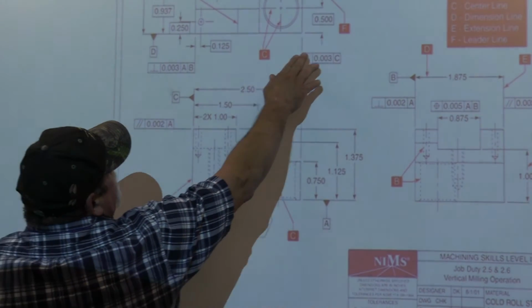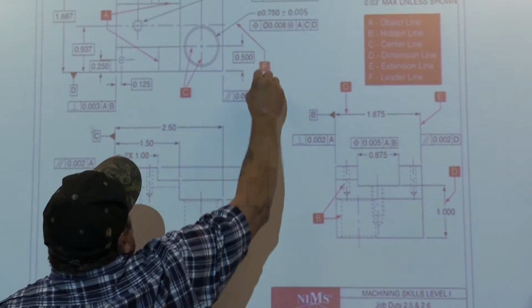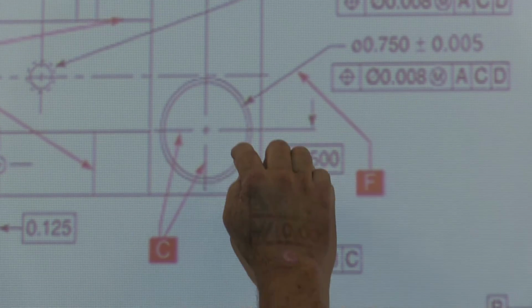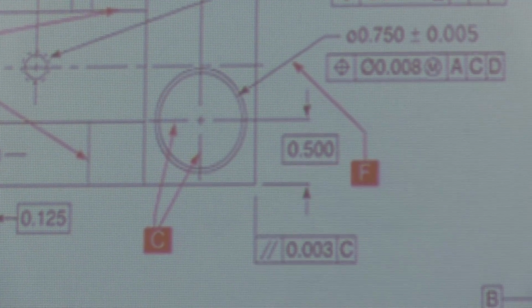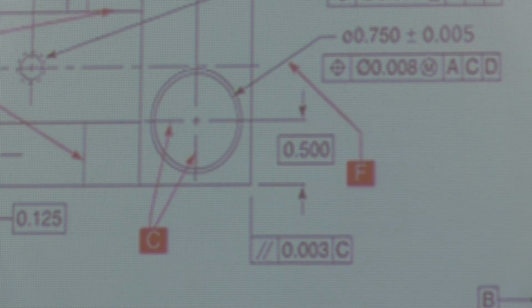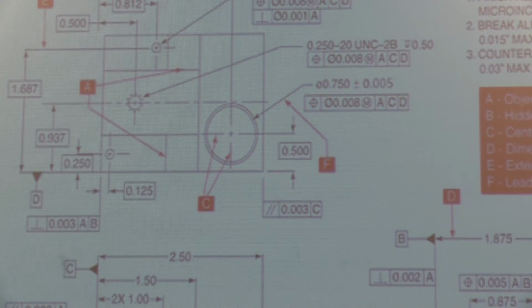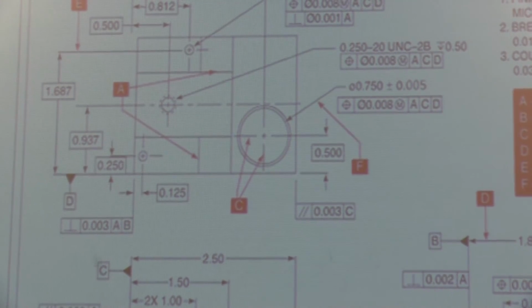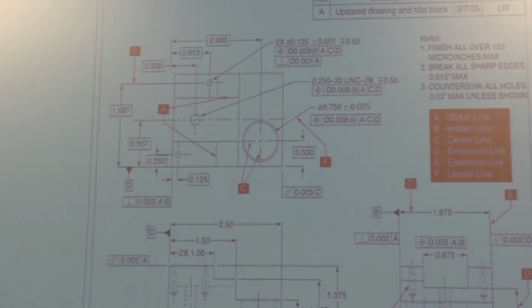So you can see here that these external dimension lines, this is a 1/2 inch to center, and it's 2 inches from this edge over. That's where you can get off over that 8 thousandths if you're not zeroed up on your part. That's how that happens.